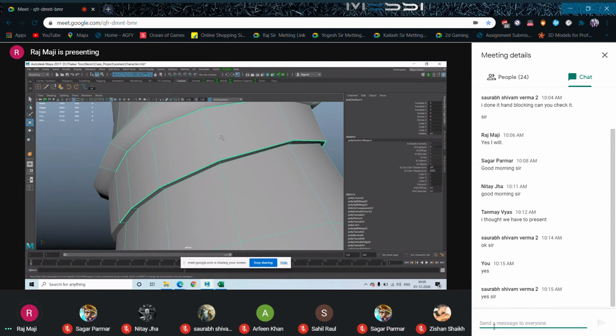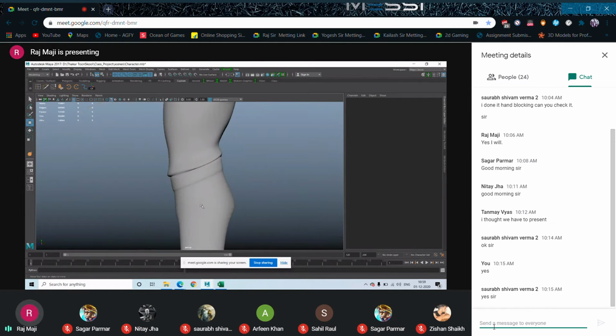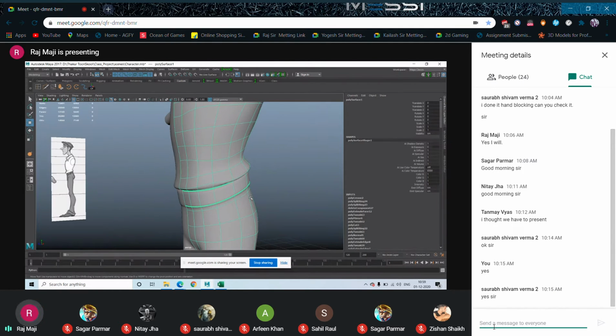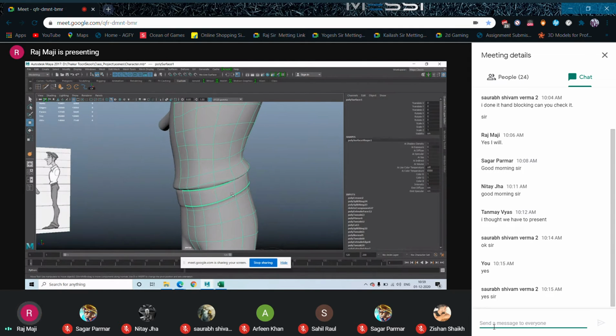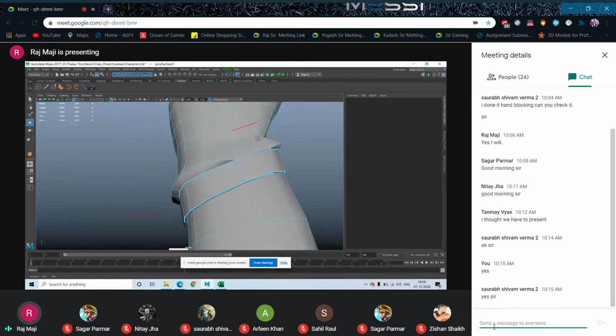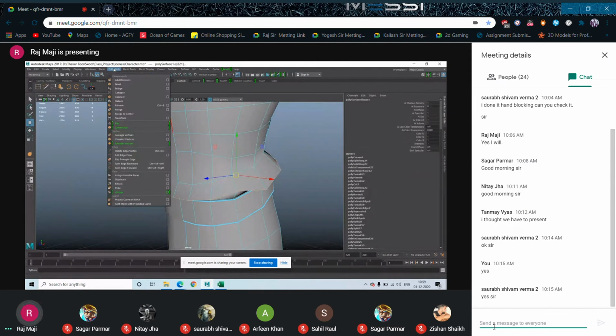So now pressing 3, can you see the thickness now? So by inserting double loop also this can be done. Absolutely fine. Can be done. But this is another way I wanted to show you. So the crease. Okay. What I am feeling, maybe you are also feeling the same thing for this. Can we bevel it?